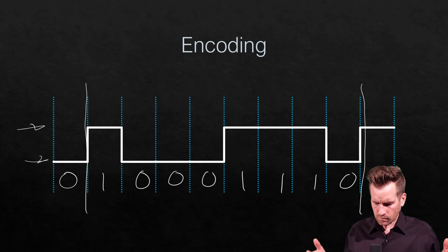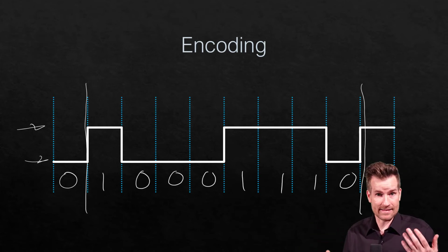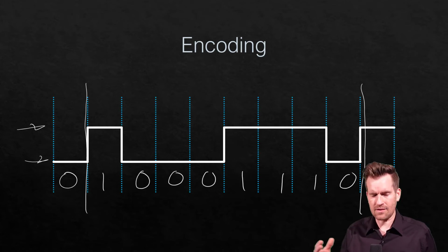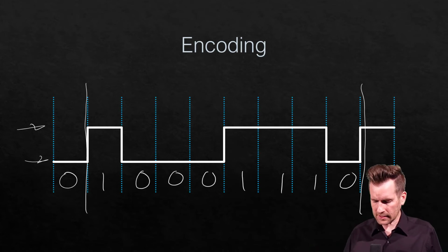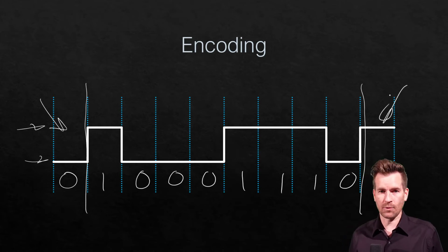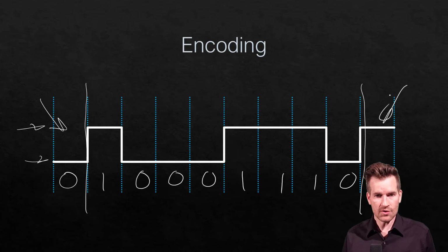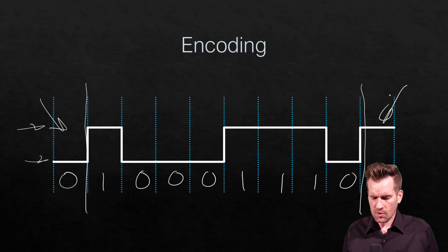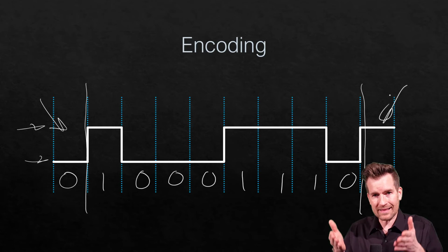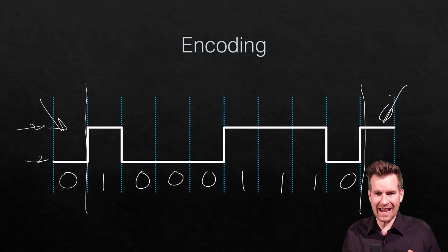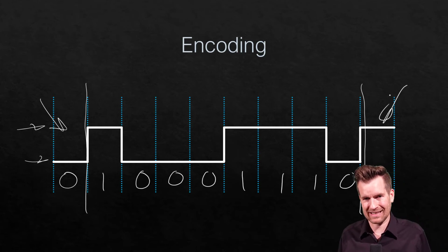And they could look many different ways depending on the encoding standards that are there. Maybe it's several bits that are flagged on each side, or this could look many different ways. But essentially here I've got a starting bit and an ending bit, and possibly somewhere in here I want to fit some parity bits, so that the other side can do a check to make sure the information it's getting is accurate. So there's going to be some sort of encoding, the order in which the bits are put in, so the other side can understand what is being sent to it.